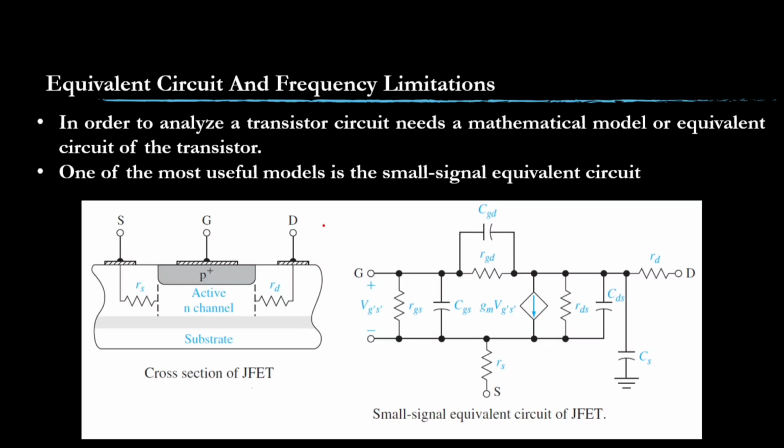Similarly, the capacitor, so far we learned, will charge and discharge, but at the same time it offers some resistance to the current flow as well. That resistance is represented as reactance, usually written XC, equal to 1 by 2 pi f C. That is inversely proportional to the frequency.